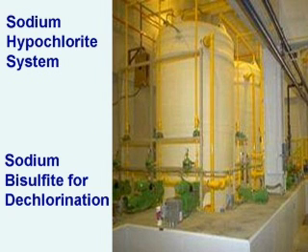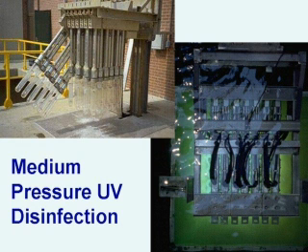This picture shows the compressed media filter. It was a Japanese technology used as a tertiary filter. It has two perforated plates. One plate moves, the other one is fixed, and there are 1-inch fiber balls that are compressed, and then you filter through those balls. What we found was very good removal from this facility, but we couldn't really compress it much because we're dealing with real dirty water, and the water would mat up on the surface real quick. So we basically uncompressed it and filtered through the media, and we got much more depth of the particles into the media bed. It took about 15 minutes to backwash the filter, but used quite a bit of water in backwashing this filter system. But the removals were very good, with very high hydraulic loading rates of about 15 to 20 gallons per minute per square foot.